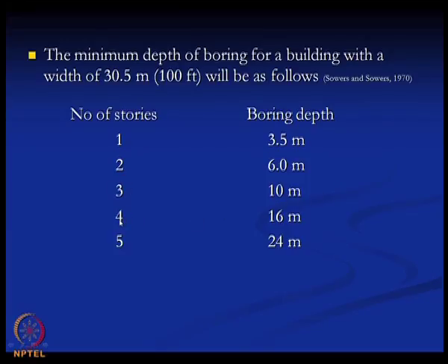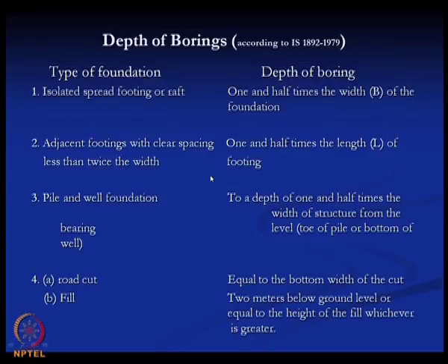If the number of stories is 4, then 16 meters. If it is 5, then it is 24 meters. So, this is a typical example shown here. Now, depth of boring according to the IS code. So, according to the IS code, what would be the depth of boring?